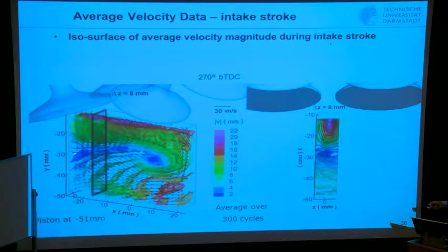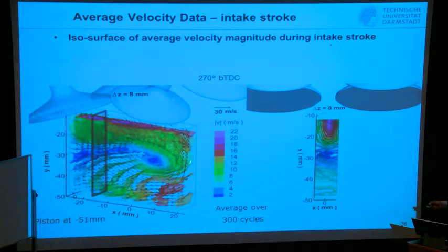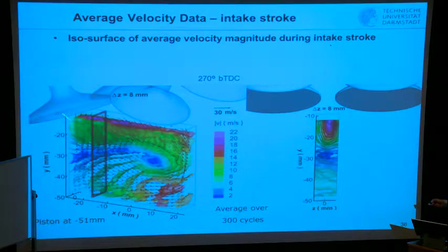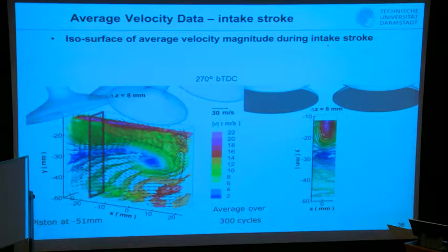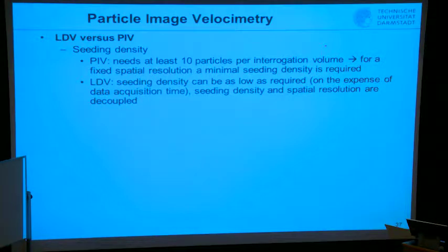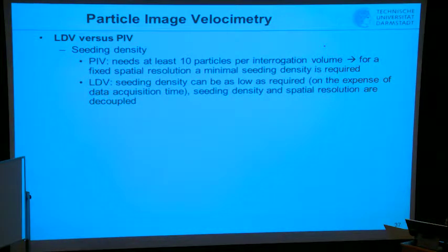You have here a stagnation zone where your flow that goes along the liner, along the piston, moves again upstream against the approaching flow, forming here the stagnation plane. And this gives you a nice idea how this tumble motion is formed already during the intake. And that can be helpful in, as I said, understanding or getting a better idea about the flow, and as well getting all derivatives and all components of your vorticity and strain rate tensor.